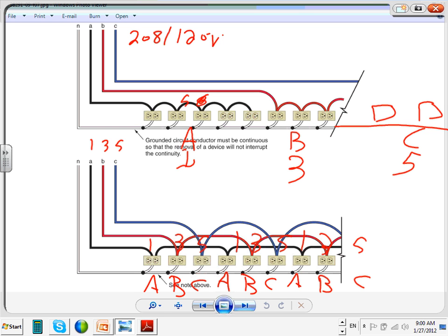Okay, so now, if I get rid of these receptacles and put lights, would that even make a difference? I can put lights here and make it a lighting system. Especially the top, instead of 6 receptacles, I can put 1, 2, 3, 4, 5 lights and feed them from 1 circuit. How, my friend? That's exactly what you guys did with Chad when you were circuiting. You're grabbing 1 phase and circuiting 1 area for it, shared with a neutral. Now we're sharing a neutral.